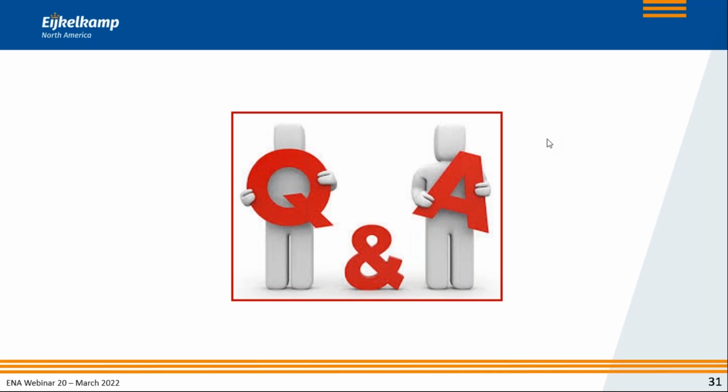And the effect that I showed you earlier, that with vibro compaction over long periods of time you see an increase in the tip resistance, I don't think it's necessarily explained by cementation, because that doesn't necessarily occur all that quickly. But indeed, over long durations of time, you are going to see the effect of cementation. After all, when you are looking at the soil behavior chart and you go to the top right-hand corner, over-consolidated or cemented soils are in there as a separate area.